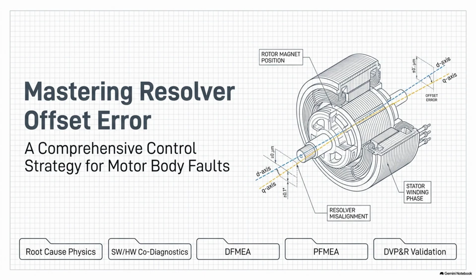Okay, let's unpack this from the ground up. Because to understand this A09 error, we really have to visualize the heart of the EV, which is the motor itself. So we have a stator, which is the stationary outer ring generating a rotating magnetic field. And inside that, we have the rotor, the spinning part that's packed with permanent magnets. And to make the car move forward efficiently, the magnetic field of the stator and the magnetic axis of the rotor have to be in a perfect, mathematically precise orthogonal relationship. Orthogonal meaning exactly 90 degrees to each other.